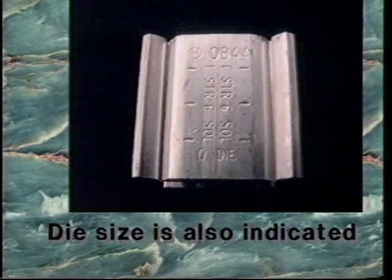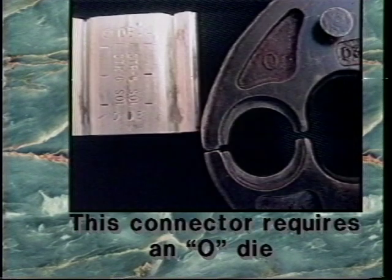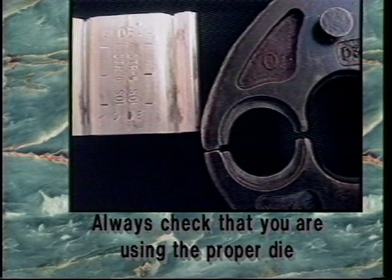Die size is also indicated on the packaging and connector. It is important to select the correct size die required by a connector. Each connector requires specific dies to provide the proper compression during installation. This particular connector requires an O-type die for its proper installation. Always check that you are using the proper die.